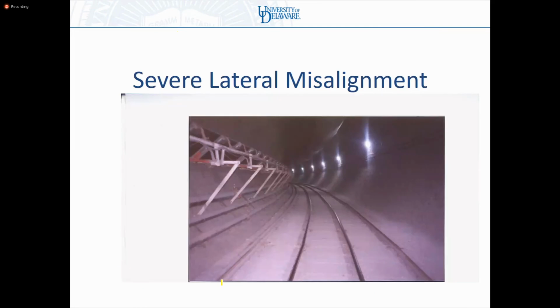So a hump is like a vertical curve? Yeah, a hump is a mini vertical curve, except we're not talking about grades and kilometers. We're talking about millimeters and meters. Okay. So I have 20 millimeters in 20 meters. That's a hump. Mm-hmm. But it's still impossible to measure a summit in this way when it's embedded.